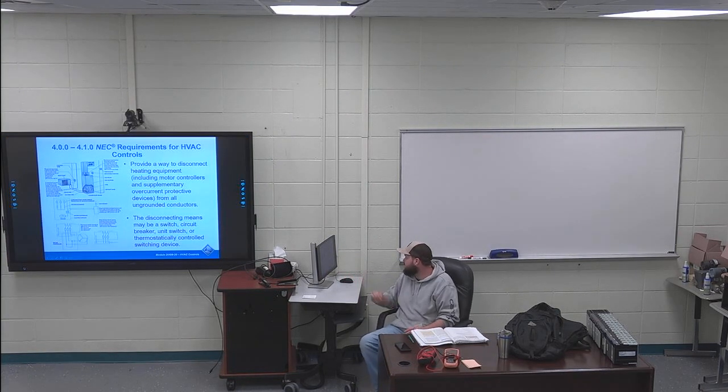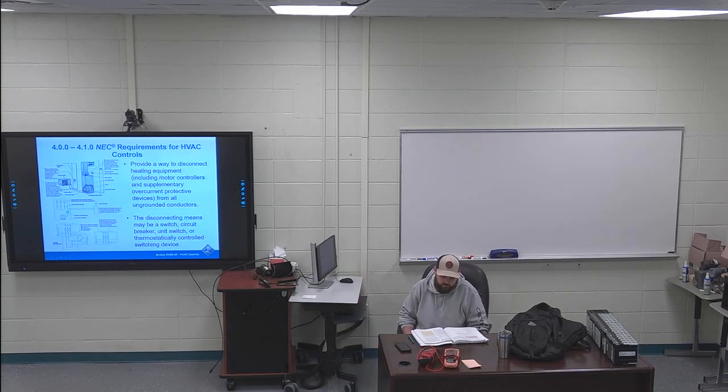So section 4 has to do with the NEC requirements. You should know how to look through the NEC at this point. I'm just going to give you the bullet points on what to look for in this stuff. 410, last sentence, part of the sentence is highlighted. I've just got NEC Article 440, Part 5 covers requirements for motor compressor controllers. That's 440 Part 5 is for motor compressor controllers.